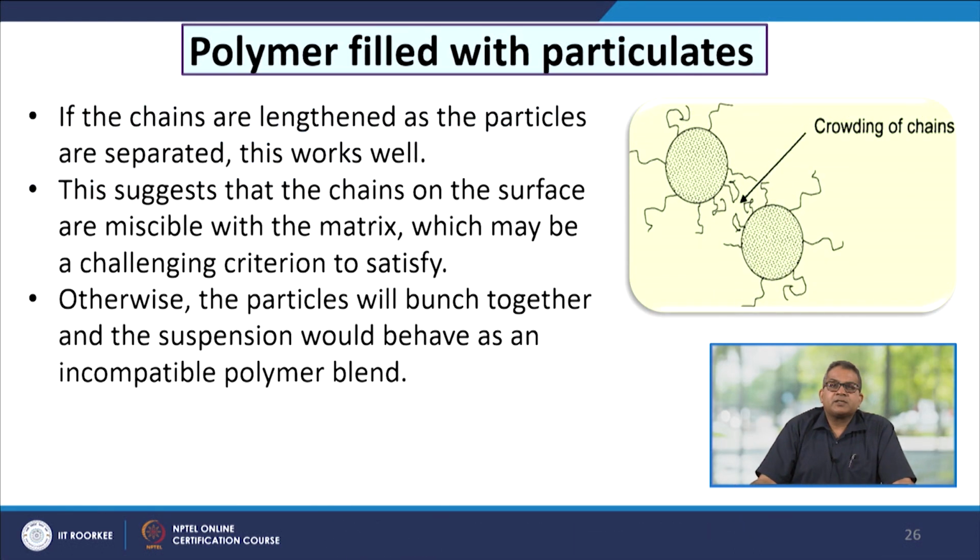Now, if the chains are lengthened as the particles are separated, this works well. This suggests that the chains on the surface must be miscible with the matrix, which may be a challenging criterion to satisfy. Otherwise the particles will bunch together and the suspension would behave as an incompatible polymer blend.